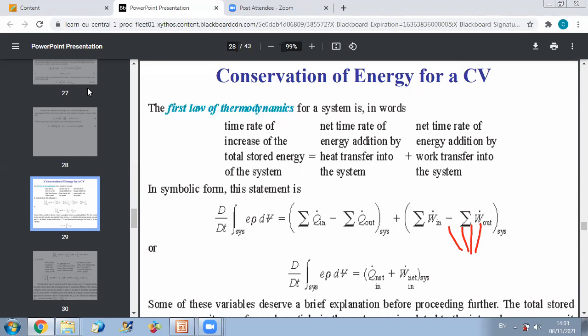Okay. So we have seen together that the Reynolds transport theorem has a variety of applications. The first one is by replacing B by 1, we get the continuity. The second one is by replacing B by V, we get the linear momentum equation. And now we will see that if we set the energy E as variable, this is the energy of a particle of a fluid, and this energy will include potential, kinetic, and internal energy.